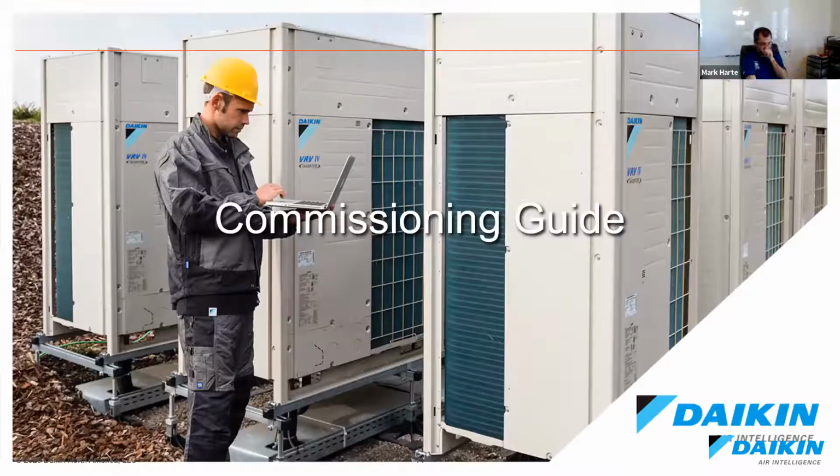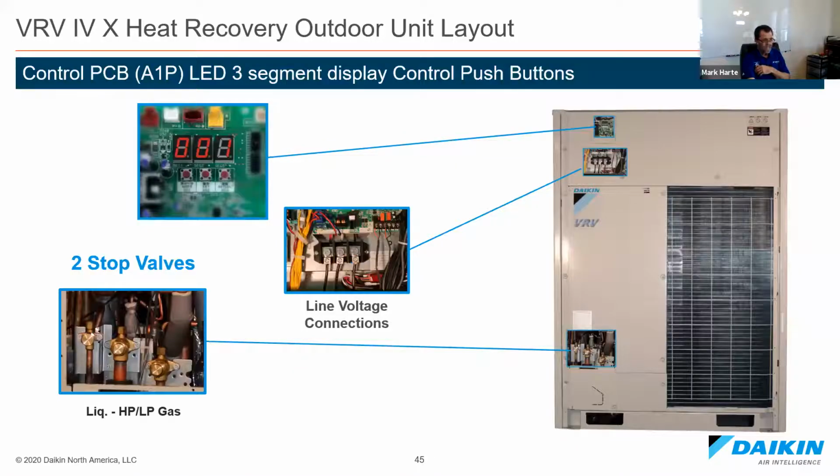All right, commissioning, starting up the system. In the outdoor unit, you're going to have a PCB with a 7-segment LED display. You see it on the top left there, right here with 3 buttons. All right, that's where we're going to do all our work as far as commissioning, depending on what we want to do. Now, any field settings we do from this PCB here affect the entire system. Okay, they affect everything. So if it's a single module, triple module, or a double module, you know, it's going to affect that system. We'll talk about those.